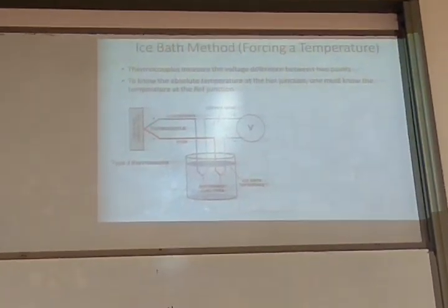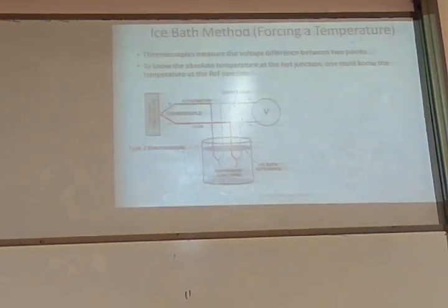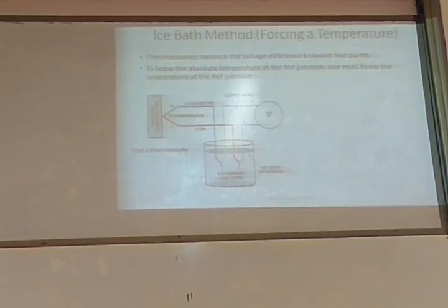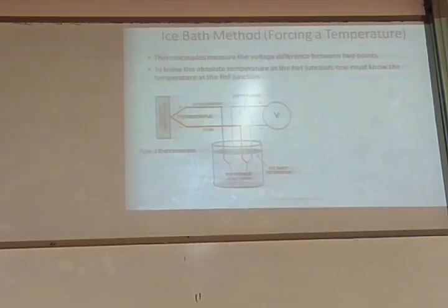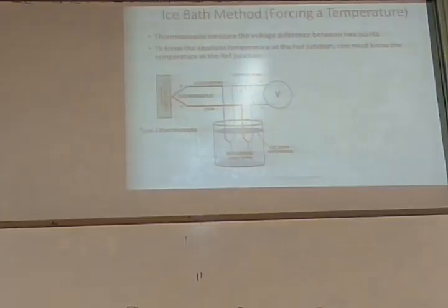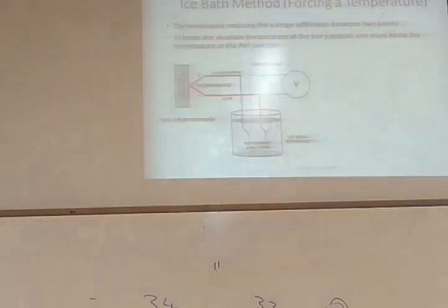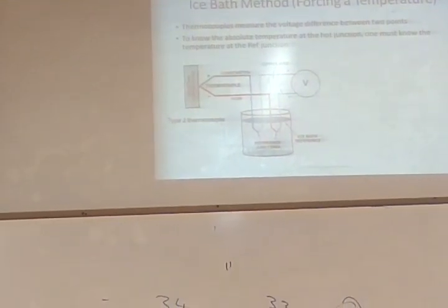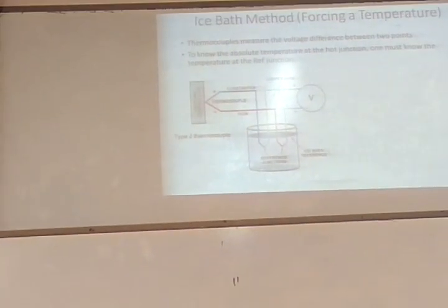Yeah, copper, it's cost consideration only. Constantan is costly compared to copper. So, sir, we could have used copper only? Yeah, very good question. Among the pairs that we find for thermocouples, let's say iron is very cheap, aluminum is very cheap, copper is also relatively cheap compared to the other materials that we use: nickel, chromium, palladium, constantan. Compared to those, copper is cheap. So copper itself we can use, copper and iron, like that.